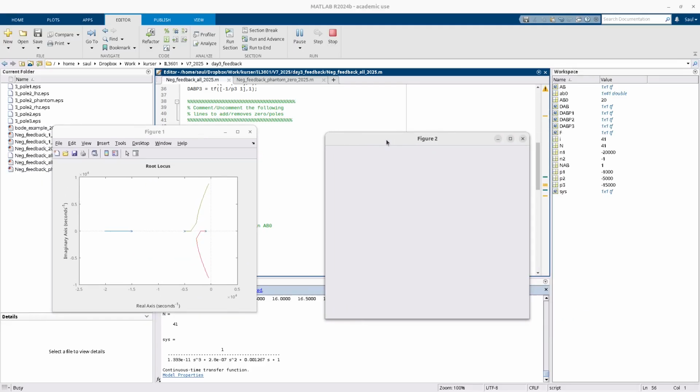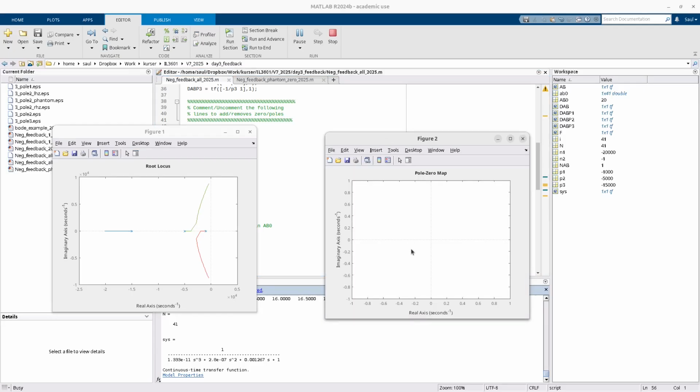So we start from a loop gain of 0, and then we start adding loop gain slowly. The three poles start interacting now, and we have the following phenomenon. The higher frequency pole starts getting far away, to higher frequencies. The two low frequency poles crash with each other at some frequency, and then split as complex poles, but something very interesting happens here. They are going towards the y-axis. So they are repelled by the third pole. And as they approach the y-axis, the system is becoming unstable.